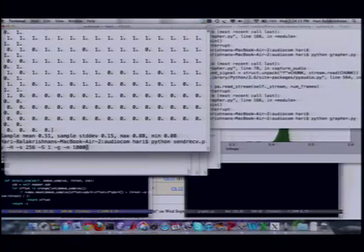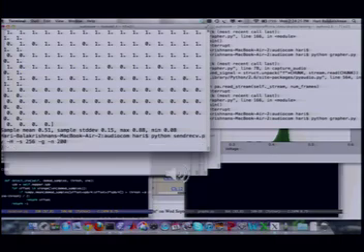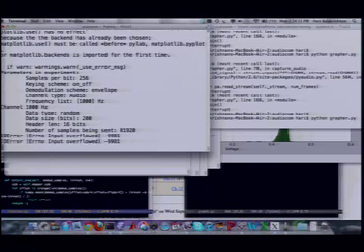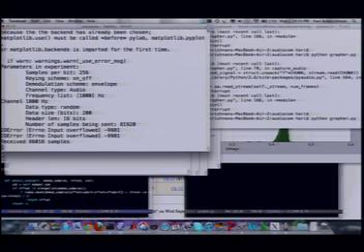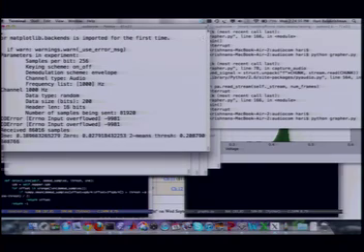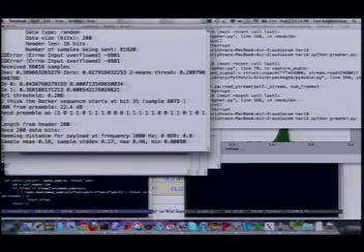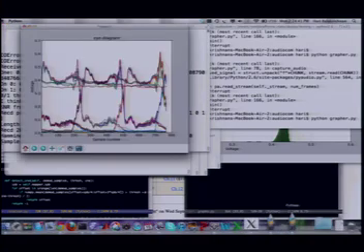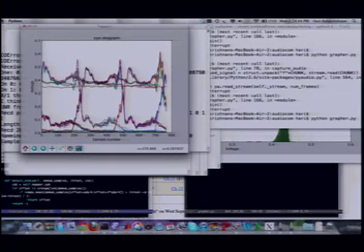Now, let's do one thing. I'm going to change this to just transmit random pieces of information. When I don't give anything, it means that the data being sent is just a random sequence of zeros and ones. Let me change this to 200 bits. All right, so we got those bits through. And that's a beautiful eye diagram. I'll explain what this means.